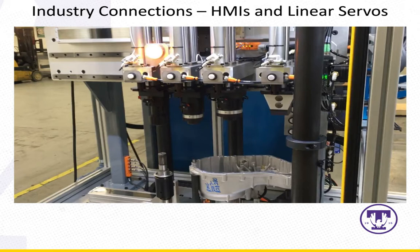And so we've talked about previously using pneumatic cylinders to provide motion in automated machinery, and that's most of motion in automated machinery. However, sometimes you need to be able to do precise positioning, and you don't just need to move something back and forth. You need to go from a precise location to another precise location, and maybe many precise locations in between those. And in those sort of applications, you'll see linear servos used, or linear stepper motors.